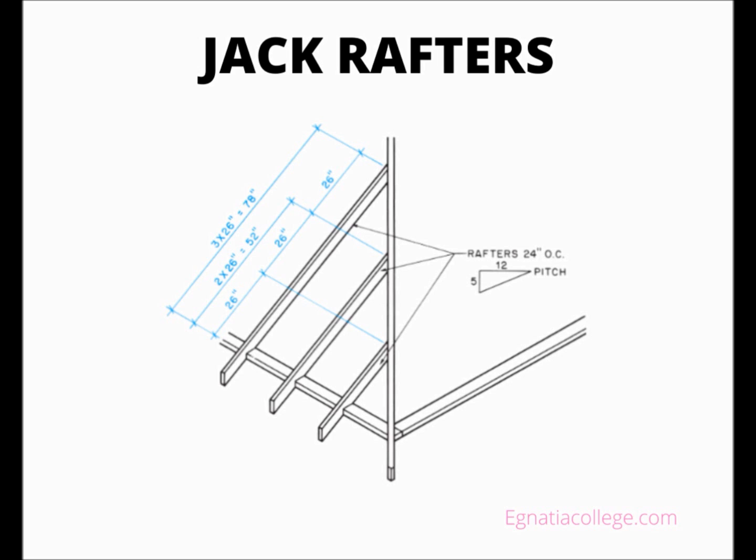The third line of the rafter table is used when the rafters are spaced 16 inches OC. The fourth line is used when they are spaced 24 inches OC. As with the other lines of the rafter table, the inch numerals at the top of the square are used to indicate the unit rise of the roof. For example, if a roof has a 6 in 12 slope and the roof framing is 16 inches OC, the difference in the length of jack rafters is 17 and 7/8 inches.